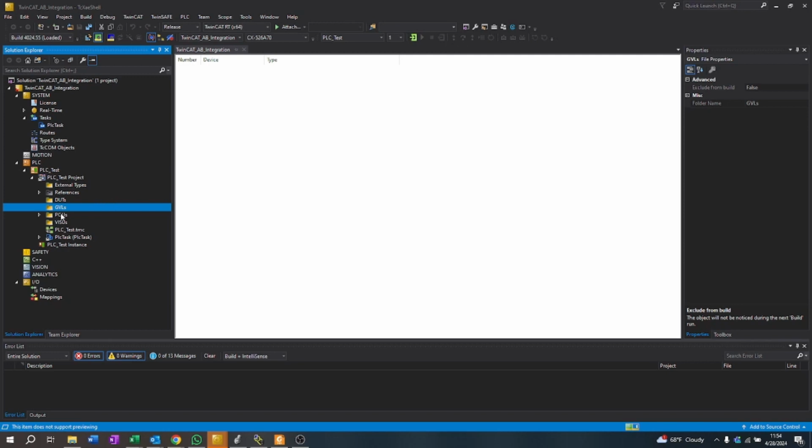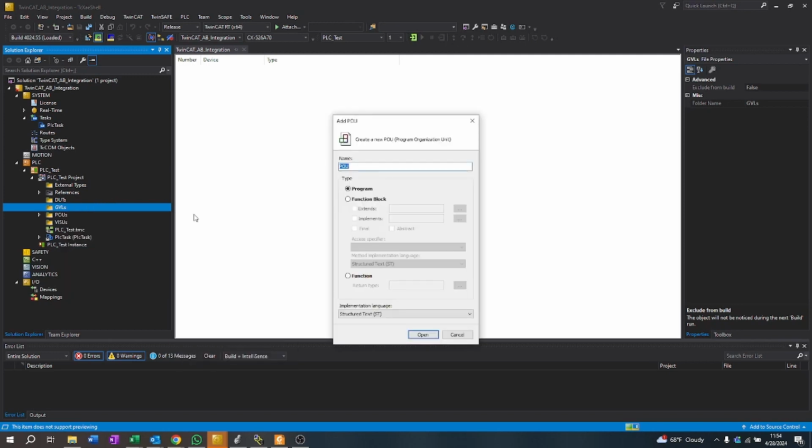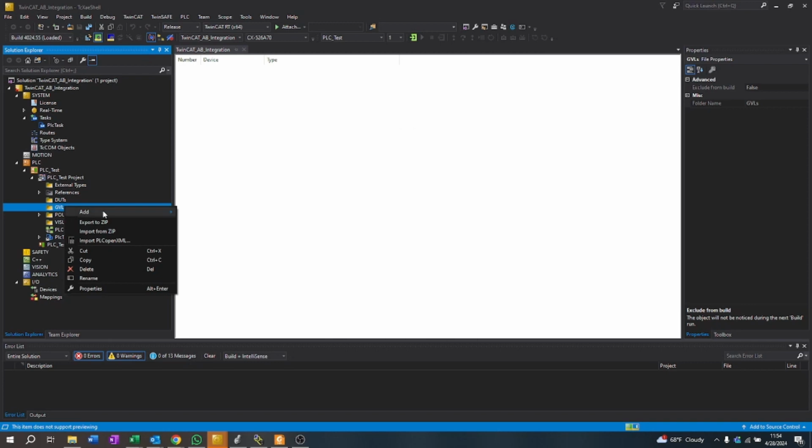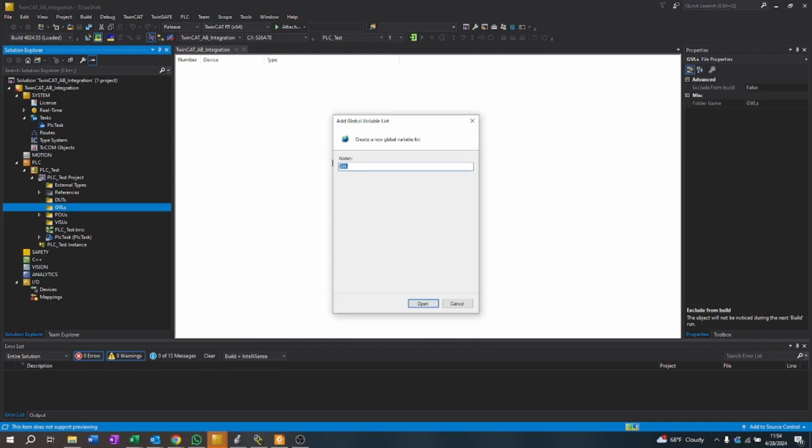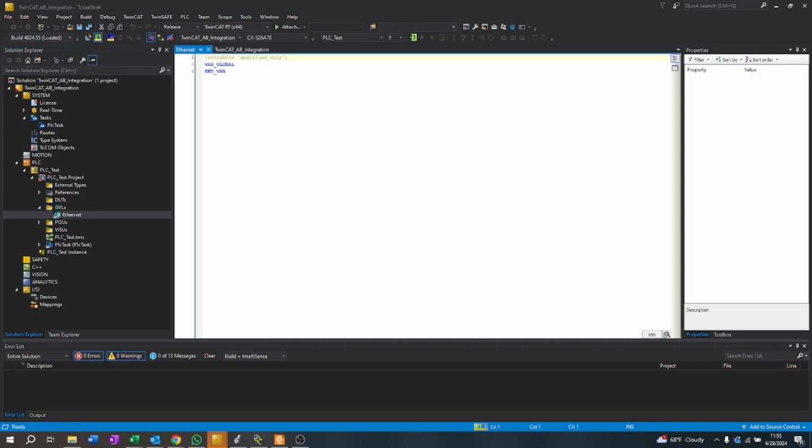I'm sorry, I'm online with the PLC. I'm gonna go ahead and create my global variable list. This is gonna be, I don't know, Ethernet. And I'm gonna create this one as, I don't know, test produced. And I'm gonna create this one as an output.